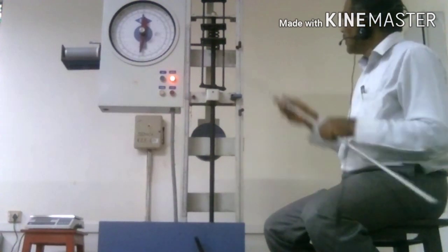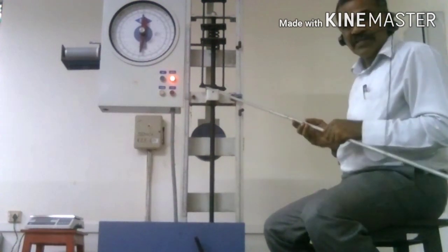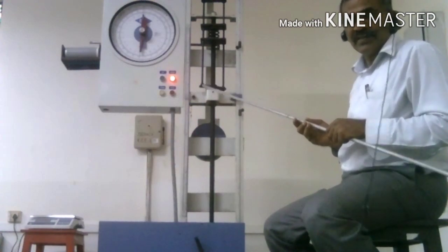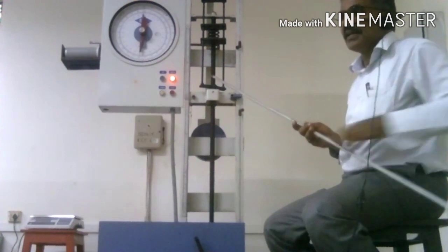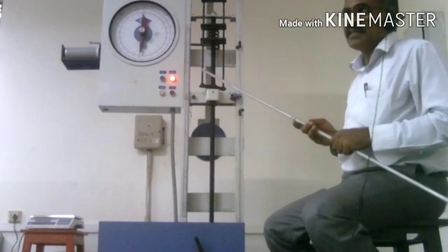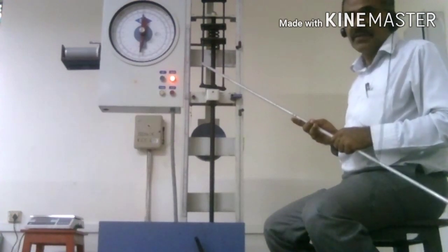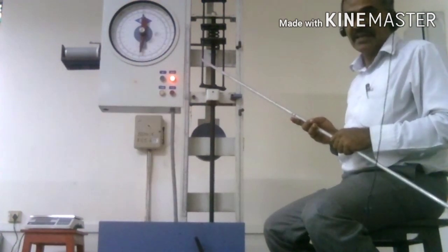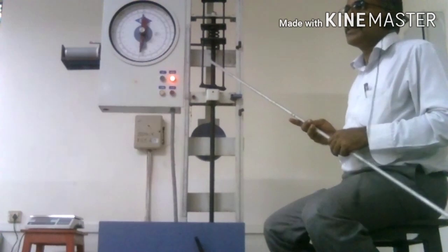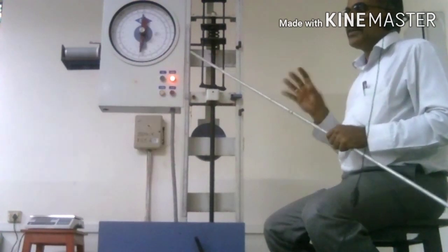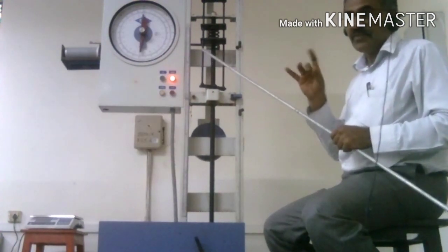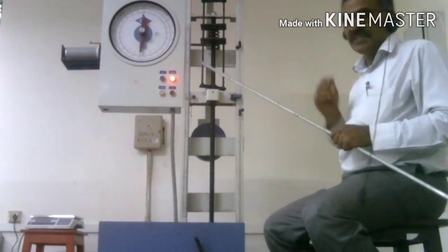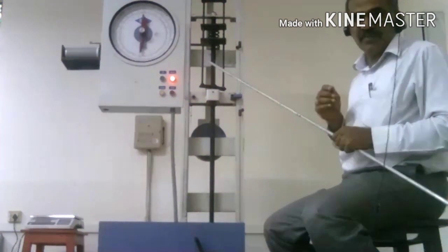So here, how to find the modulus of rigidity? We have the relation between the load and deflection. There is an equation. With the diameter of the coil in terms of radius, the equation will be delta is equal to 64 W R cube N by G d power 4. In the equation, we know the compression of the spring, delta, and the load is known. And you can calculate the value of G, the modulus of rigidity.